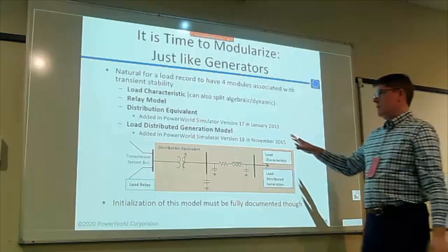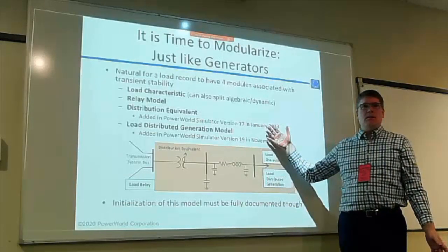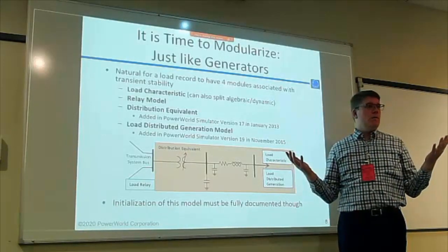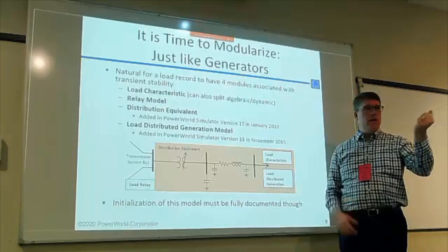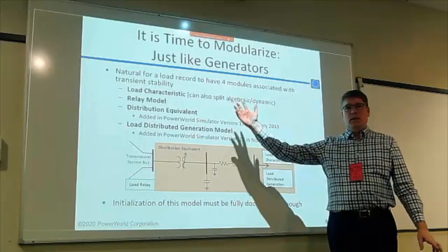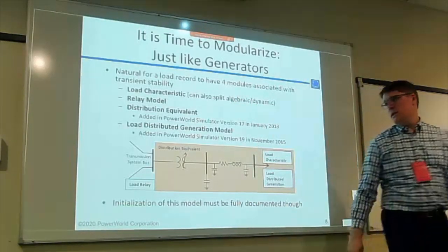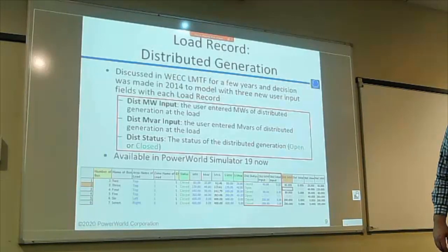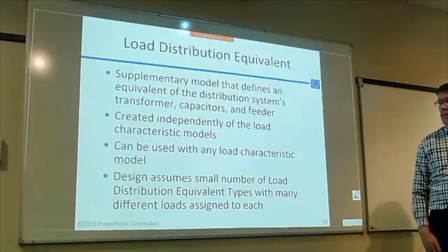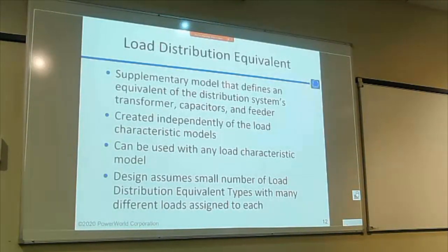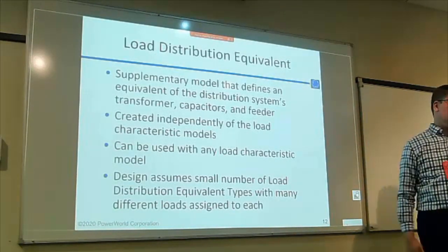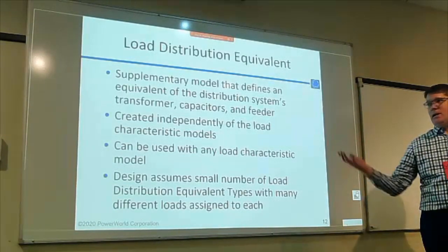So the CMPLDW, the reason it has 130-some parameters is because it's really like 6 or 7 models in one. It's got a feeder, it's got 4 motors, it's got an electronic, a static, and then the distributed gen now as well. I'm pretty impressed you can solve all of that different stuff. Yeah, and it got slower. Part of the growing pains of switching to the composite load model is all the simulations got slower. Because why? Well, because you're modeling a lot more.